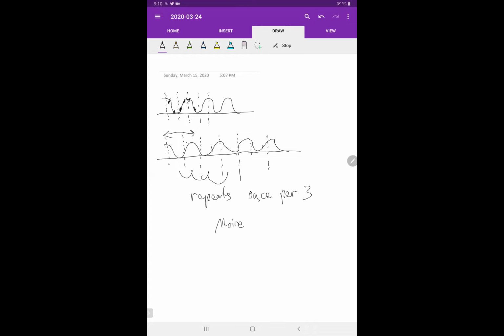Anyway, the takeaway lesson from this is that, yes, in principle, you could make a semantic argument that the minimum peak spacing is 0. But if you want to see a feature, first of all, you need non-zero peak spacing. And second, you need pixels that are at least half of that peak spacing in order to be able to see it. This is also called the Nyquist limit, because Nyquist, either a mathematician or electrical engineer, proved that in order to detect a signal at a certain frequency reliably, you need to sample at least twice per cycle of the frequency.